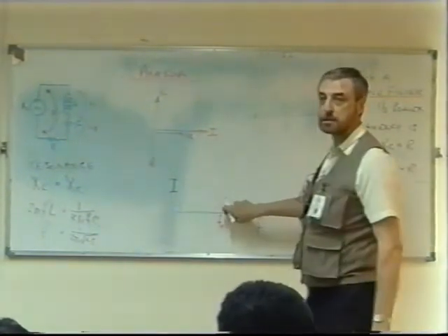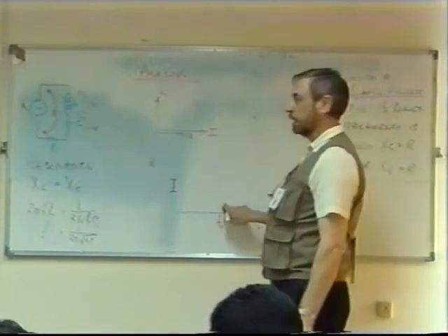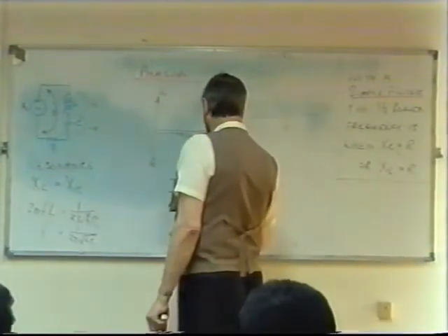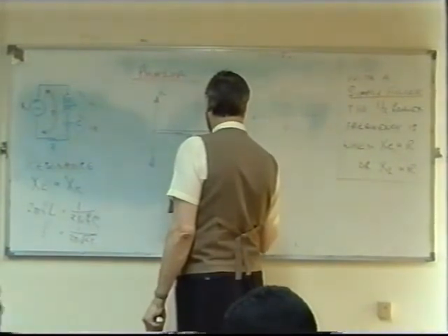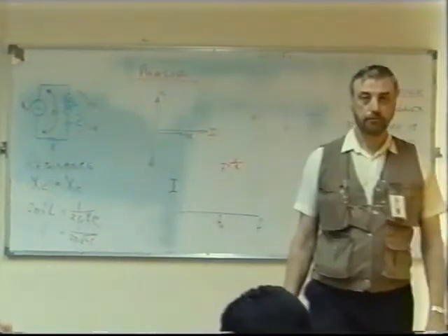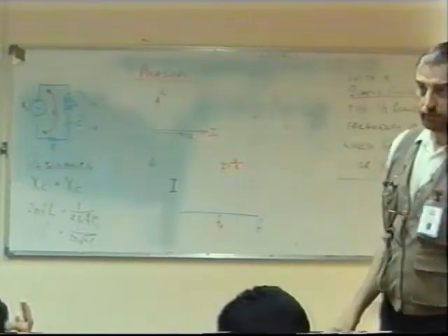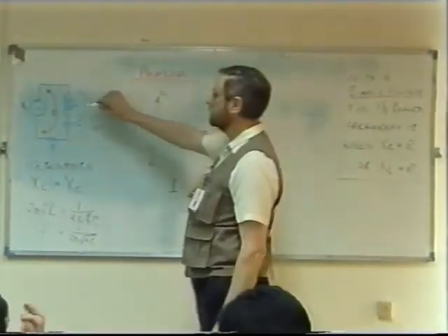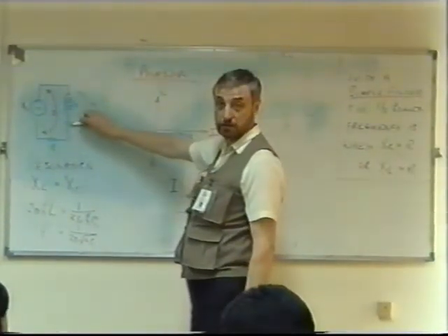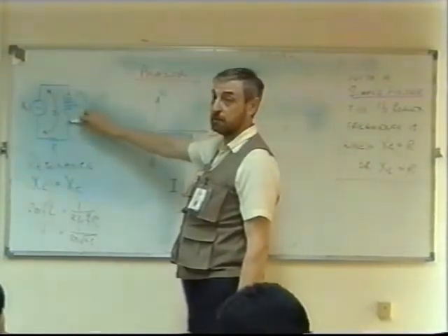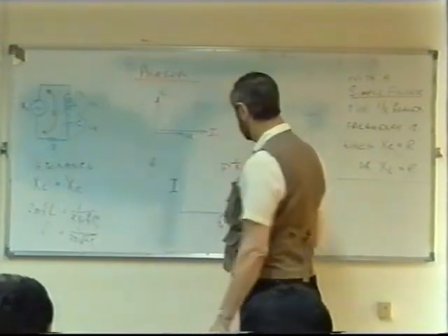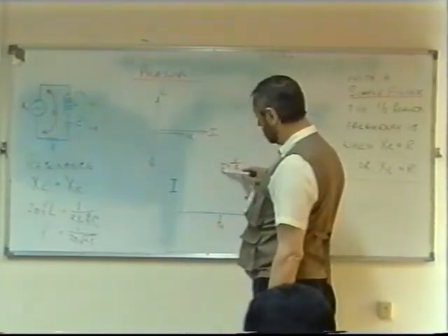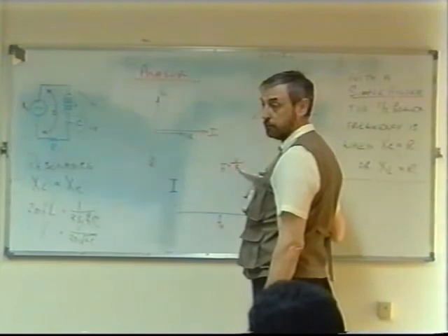At resonance, we get a certain value of current flow around the circuit, which is equal to the voltage supply divided by the resistance. Do you agree with that? Yes. Because remember, these two reactances effectively cancel one another. Their back voltages are opposite, so we can ignore them. And the only current that flows will be the current V over R.